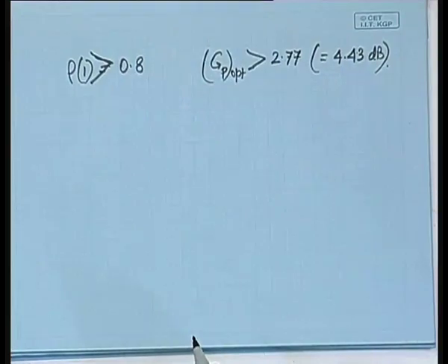Each bit of increase results in an overall bit rate increase, but it boosts the signal to noise ratio by 6 dB. In this case 4.43 dB is quite pessimistic. If you take rho 1 in the range of 0.9, because that type of correlation quite often exists, then without increasing the number of bits you can have 6 dB of improvement just by switching over from normal quantization to predictive quantization, or what is called differential quantization.